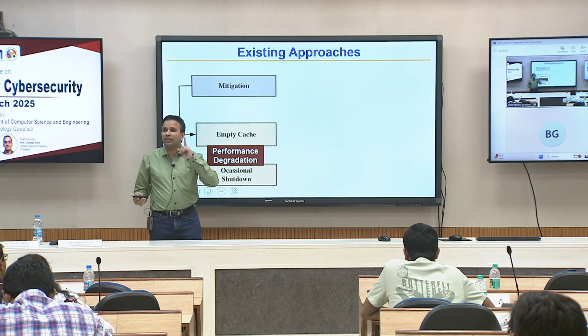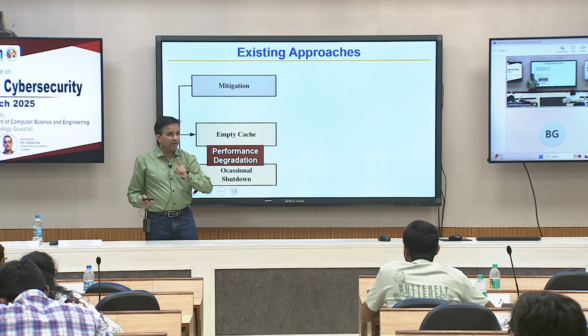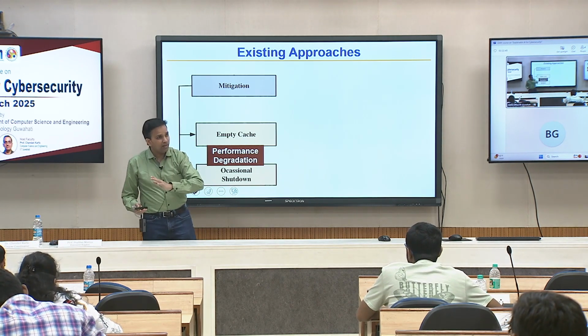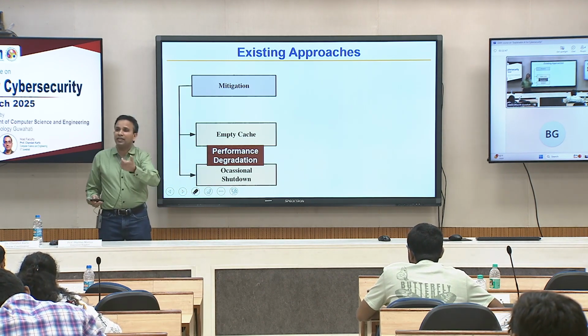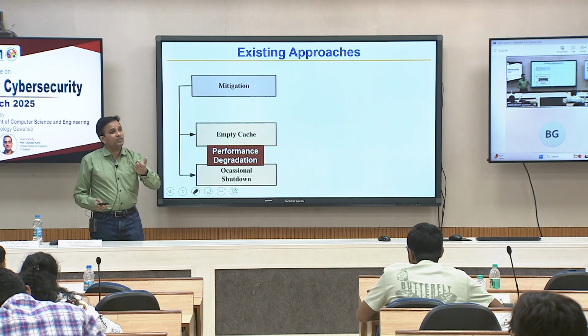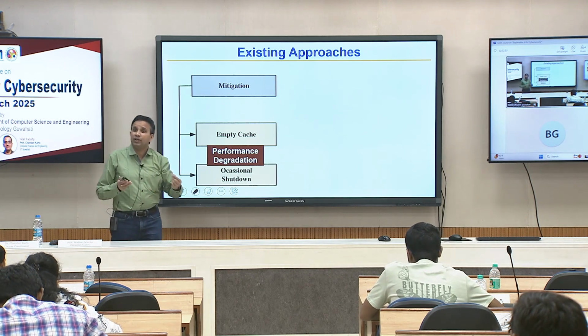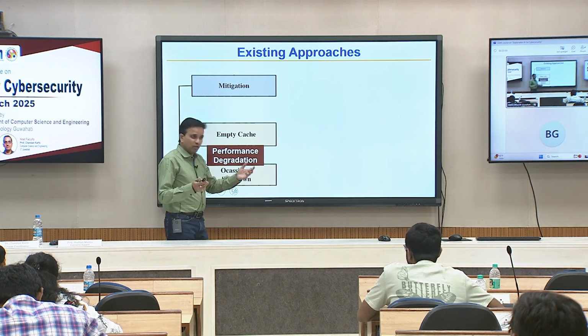Every instruction, you have to wait at least one cycle for the decode to realize it is not a branch. If it is a branch, you have to wait longer. If it is unconditional, then you know the target after decode. If it is a conditional, you have to wait at least one more cycle for execution, to figure out the condition. If it takes longer, you have to wait.